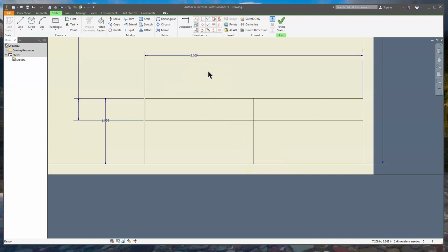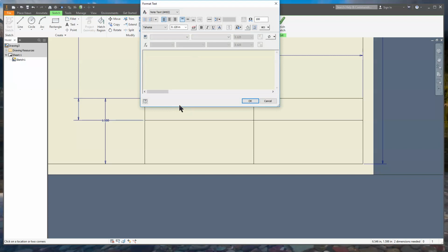So in our drawings, we want to have these fields or elements in our drawing border to tell us information, title, and so on. So I click the text box. I click in this space, it brings up the text box, and I highlight this and say I want this to be a little bit smaller for those element names, field names. I'm going to tell it that I want it to be 1/16 of an inch, which is 0.0625, and you can see it went smaller.